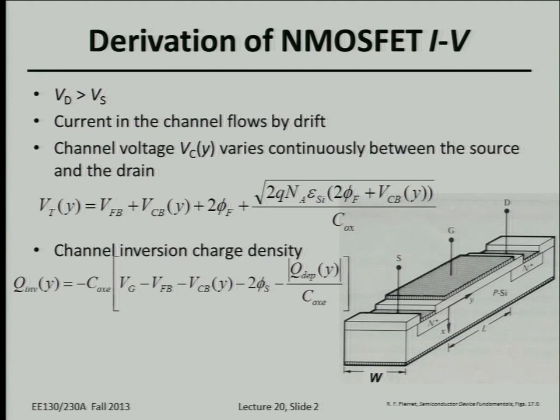As we know, for the current mechanism across the MOSFET channel, when the gate voltage is over threshold, there will be the drift current by the electrons. And also, the most important parameter for us to figure out the drift current is actually the threshold voltage, right? So basically, only when the gate voltage is above the threshold voltage are we able to drift electrons to form current.